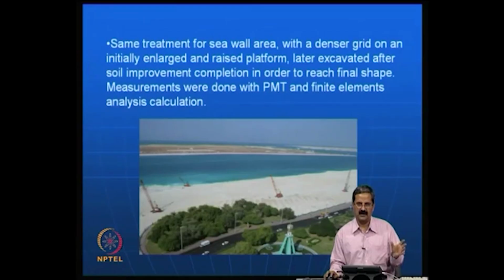For this technique we have seen the design, using a simple method in which you can design based on the weight available. You can design the height of drop and the spacing for the required depth of improvement. The required depth depends on, for example, a significant zone of 2B. If you have a footing of width B, 2B is the significant depth of the pressure bulb. So one must be able to calculate the significant zone. Even using finite element calculations, you can simulate the whole structure on top of the soil and understand where the stresses are coming.